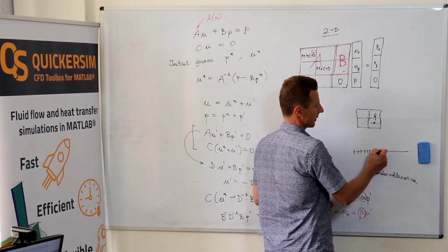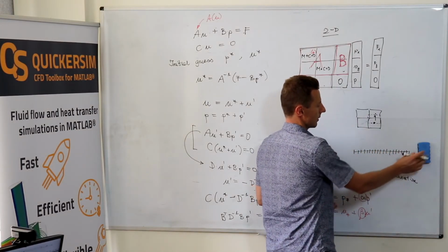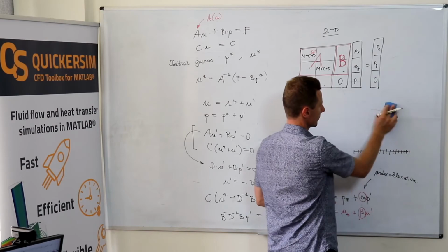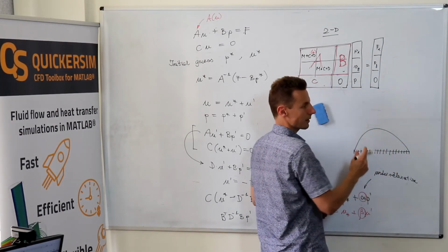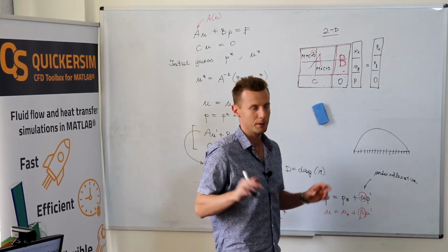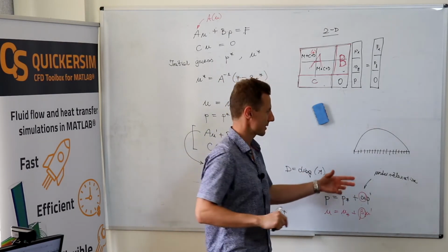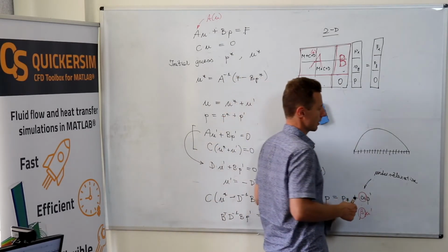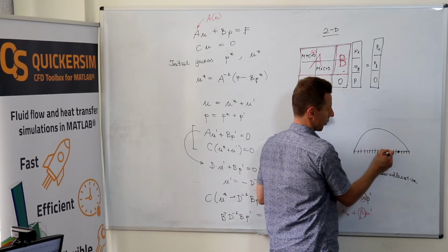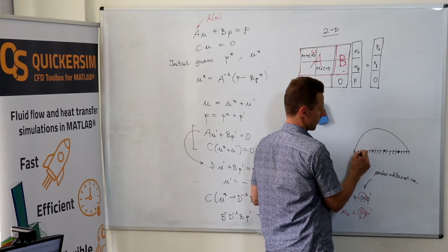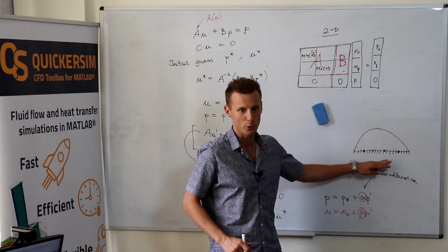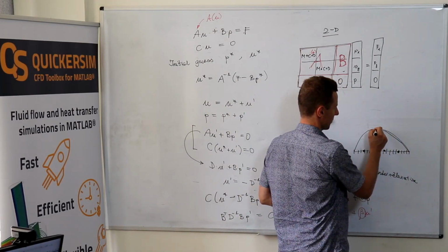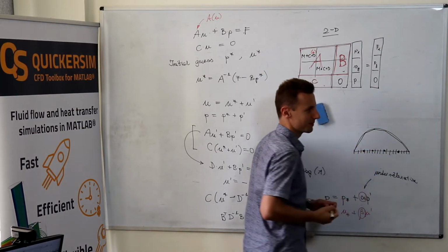a 1D finite difference mesh and you want to solve, let's say, a heat conduction problem, and it looks like that, for example, and the very naive explanation of the concept of the multigrid method, not algebraic multigrid method, is, well, if you take a coarse mesh, you got many fewer unknowns in the system, and you would still come up with something that probably looks like that.